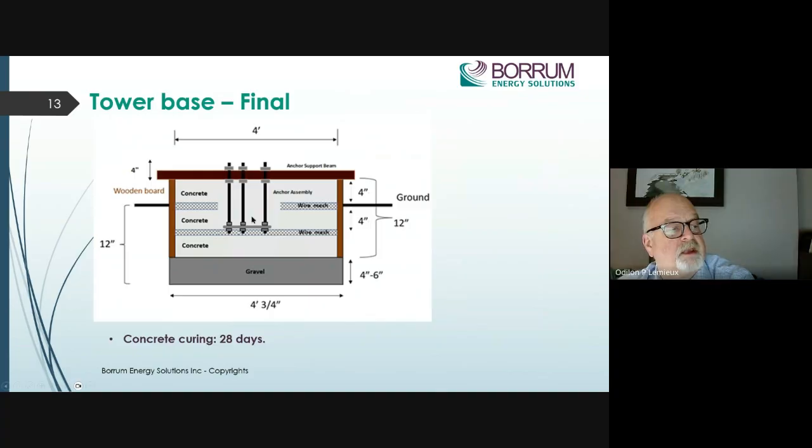Then you have the concrete cast that's sitting here with the support beam, being held by the side of the form, so it doesn't go down further than it needs to be, but it will be at the right height by the time the concrete is cured. So with concrete, we get another wire mesh here, and you put more concrete. So you fill it up. At the end of the day, this thing is 36 bags of concrete at 4,000 psi.